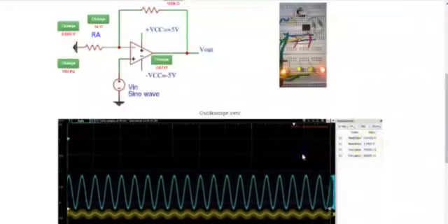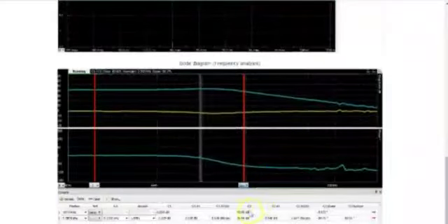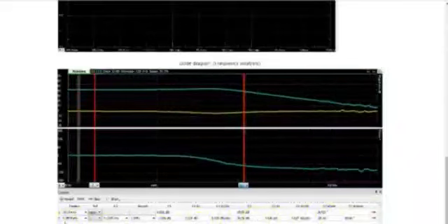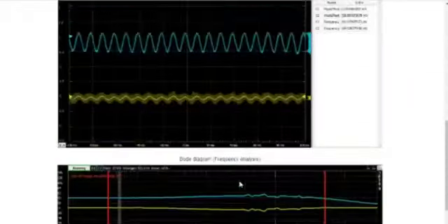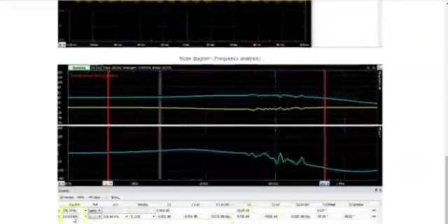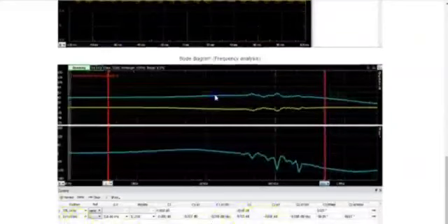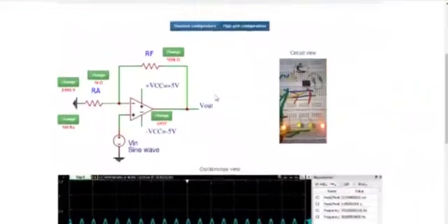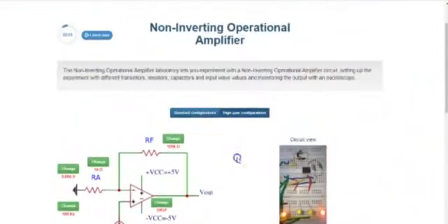In the Bode plot, the DC gain is 40.11 dB and phase is almost minus 0.172 degree. The 3 dB bandwidth is found to be as low as 9.3 kHz. A similar analysis for OP37 shows a DC gain of 40.08 dB and a 3 dB bandwidth of 517.03 kHz. This again confirms that op-amp with better performance specifications will have greater 3 dB bandwidth and closed-loop gain.